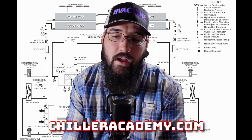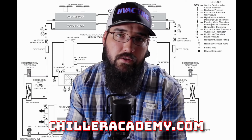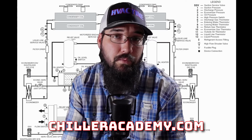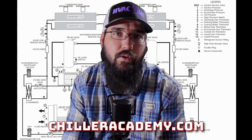At the same time, some of them even take it a step further and put a hot gas bypass in on top of that. So you talk about some crazy unloading ability, and there are dangers to doing that from a compressor perspective, because you run risks of not being able to cool the compressor properly, not being able to maintain enough differential. And that's one of the things that's really critical for a screw.